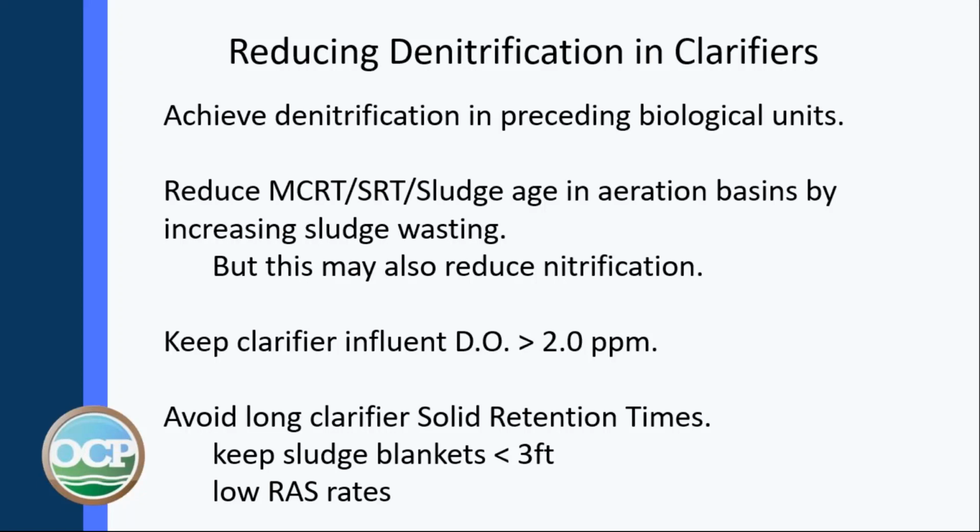Avoid long clarifier solids retention times. Again, waste frequently, small quantities. Keep the sludge blankets less than 3 feet deep. And keep your return activated sludge rates as low as possible.